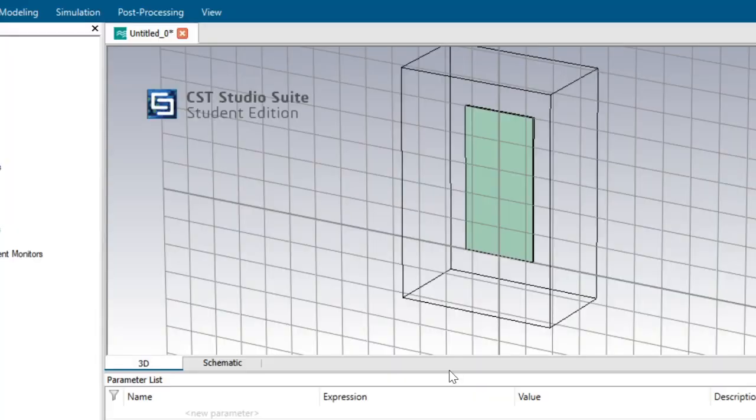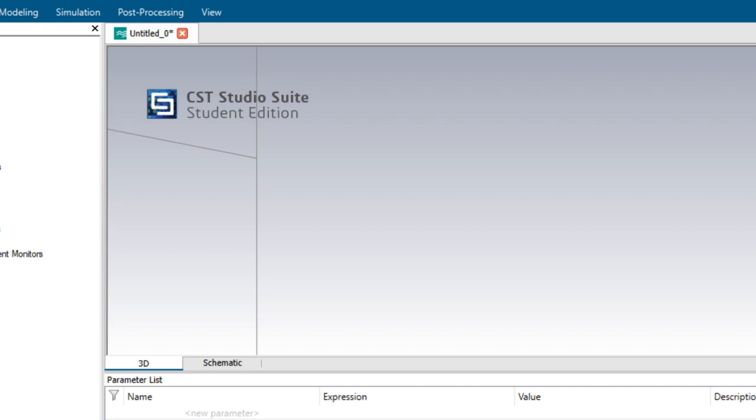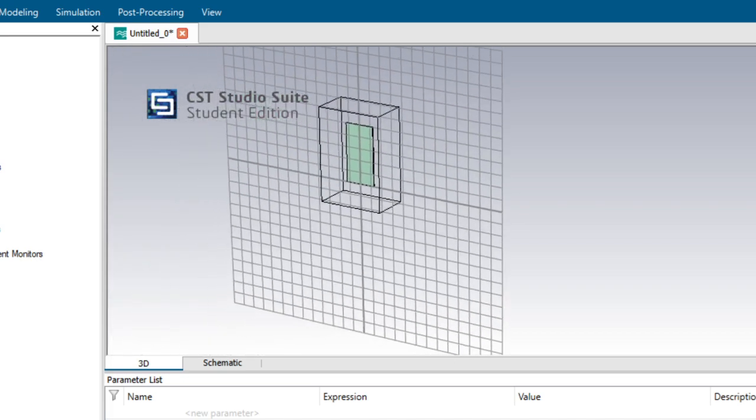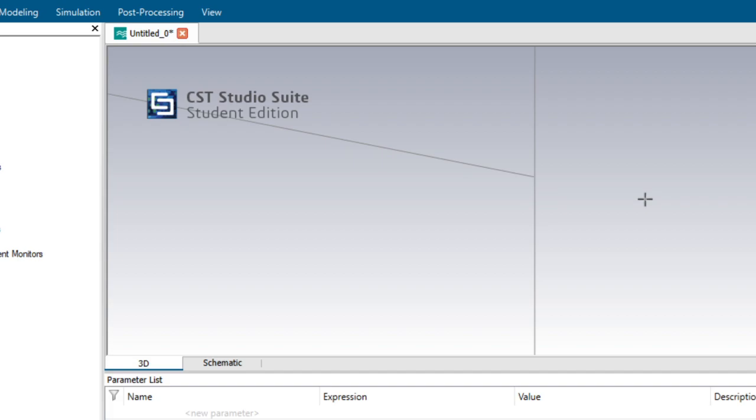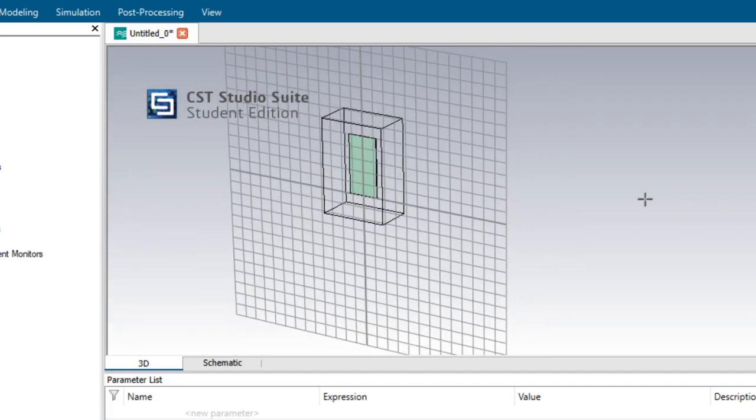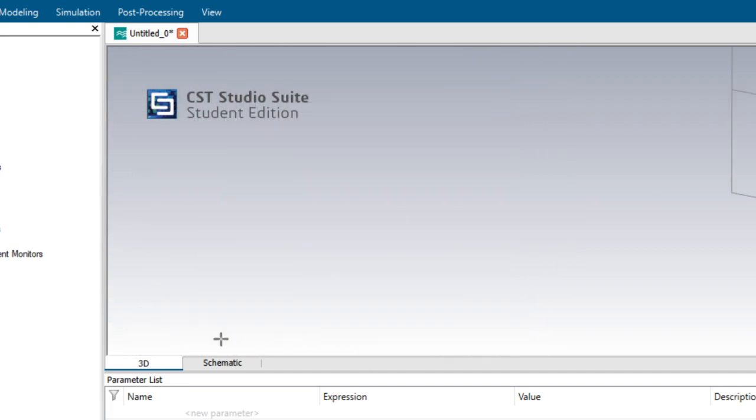Fine. Now, can you tell me, using that AppCAD software, the analysis and synthesis of transmission line, what is the width of the line that we had got? Tell me. I believe that everyone has noted it down. 2.93. Okay, so 2.93 is the width of the strip line.